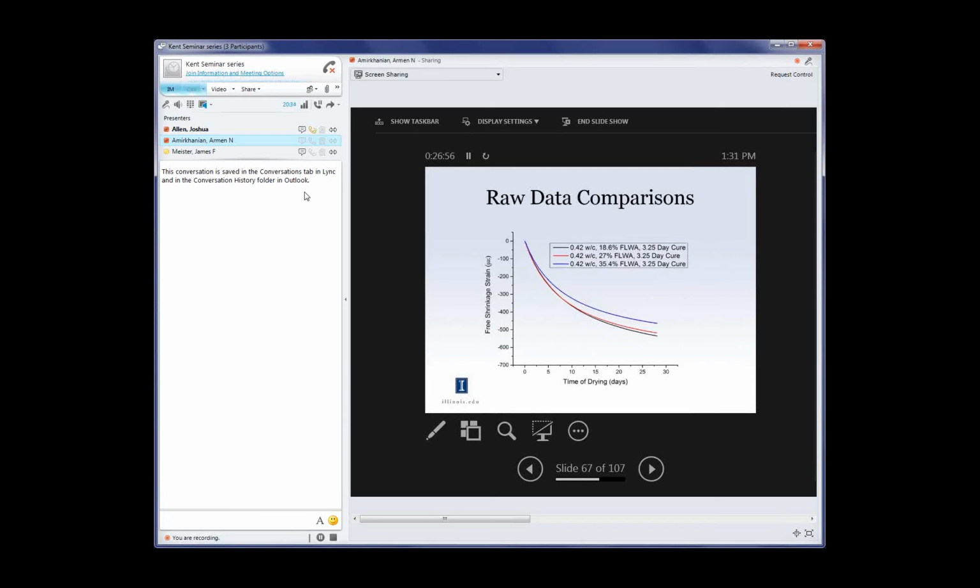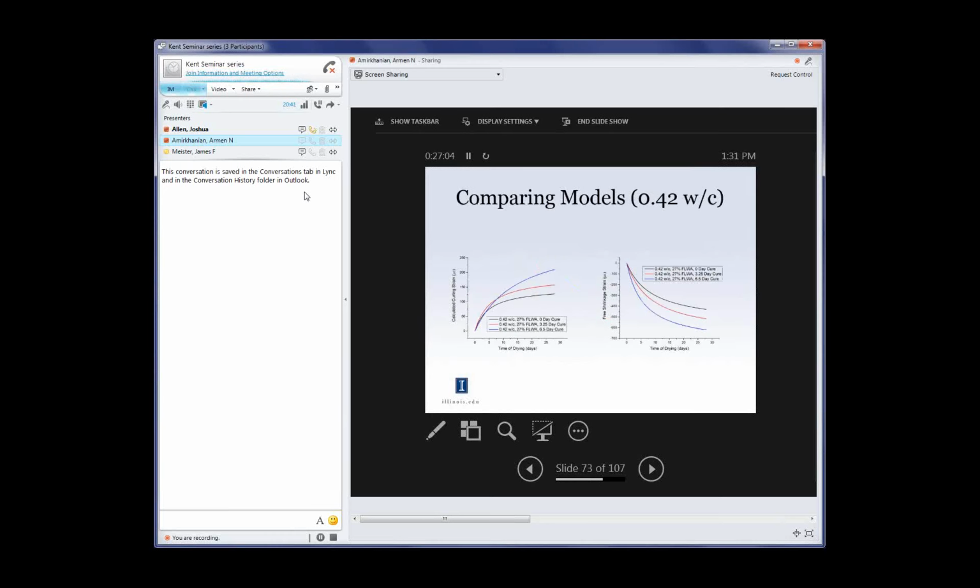And here we have the lightweight content. I'm going to skip through that one because it's a whole lot easier to compare the curling strain to the free drying shrinkage strain. So the colors match up. As you can see here, at 6.5 days, we have the most curling and also the most free drying shrinkage. And the trend holds for the other two specimens. So the free drying shrinkage is also filling in part of this picture of if we have more water loss, we see more curling.